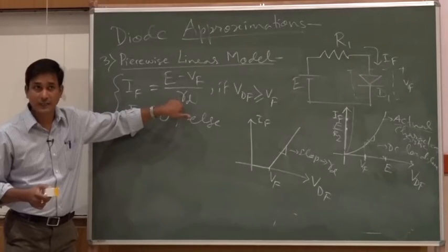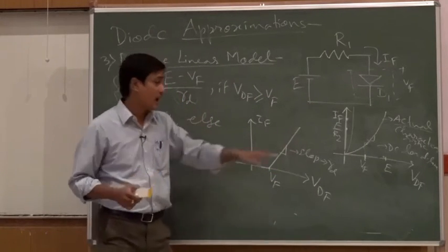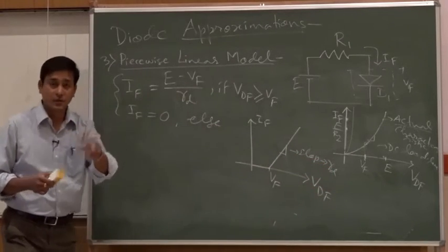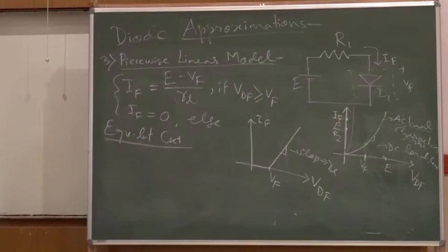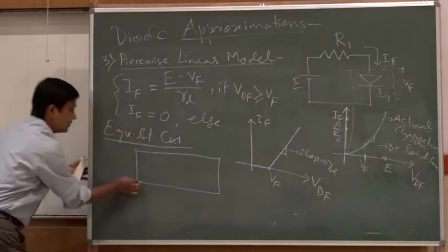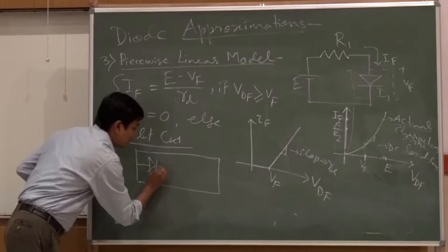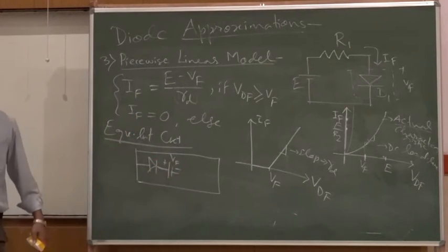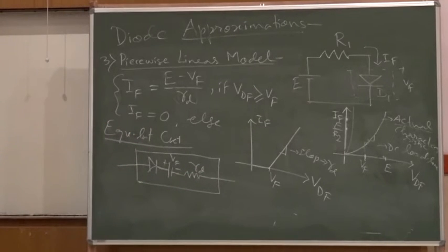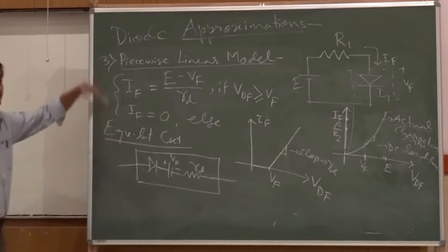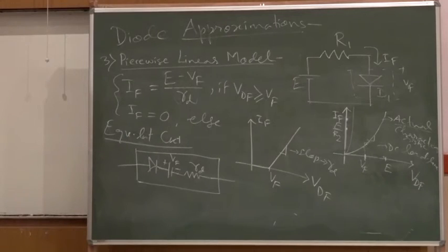Rd. If I am talking about the diode and its resistive action, I can consider in the equivalent circuit some resistance for the diode itself. So if I consider the electrical equivalent circuit we described earlier, this was the block in which first an ideal diode will be there, another part was there just like earlier, plus minus Vf, along with that one resistance has come, that is Rd. What is the difference from the second model, where we considered constant voltage drop only without any Rd? In that case I will say Rd is 0, otherwise the remaining things are the same.